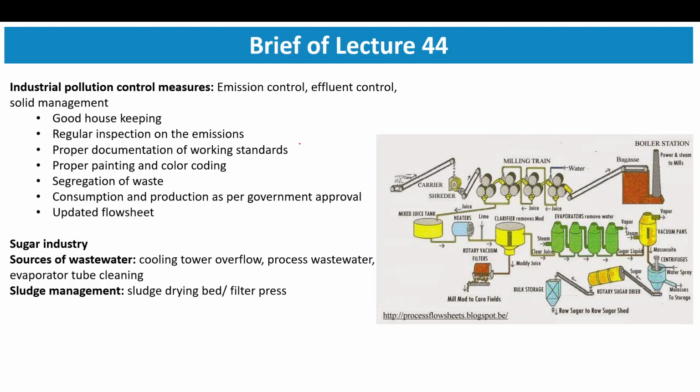Then, proper documentation of the working standards. You need proper documentation at regular intervals of the parameters obtained for all the processes. For example, if you are treating water and removing organics, you need proper monitoring of BOD and COD at specific intervals of time, and properly documented data for that. That way you will be able to find out if there are any flaws in the process, after what point the problem started, and what the probable reason could be. These types of documentation help in diagnosing problems that might happen.